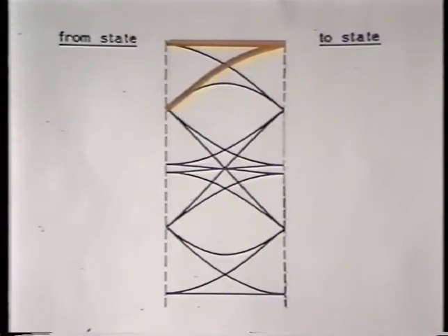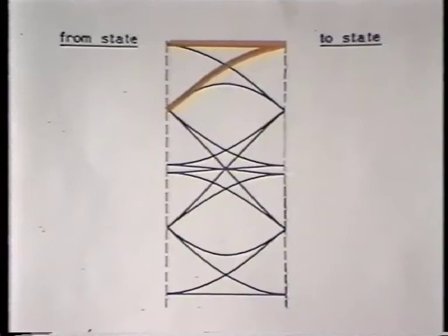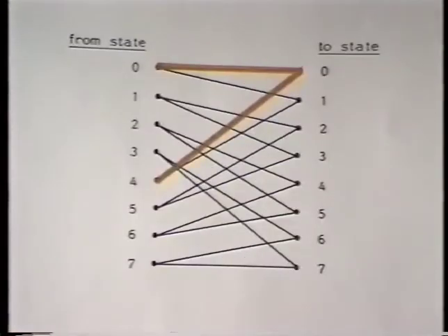Here we see one such section. This is the periodic part of the phase trellis. The left hand is the input state and the output is on the right hand side. The two yellow lines correspond to the choice the Viterbi algorithm has to make every symbol interval for every state in the trellis.